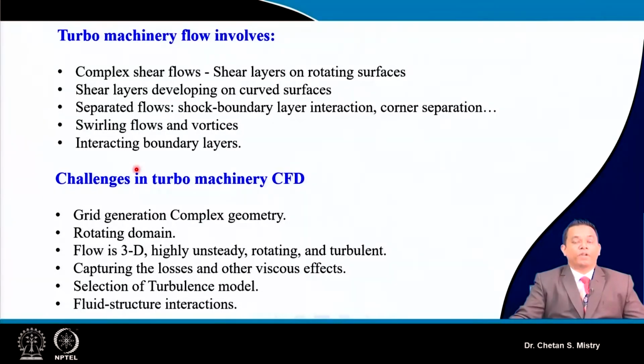Now, when we are talking about the application of CFD, there are certain challenges. The very first is the generation of grids. That means in order to discretize the fluid domain, we know our blade shape, which we get using different approaches, say different wall distributions, that give the three-dimensional shape to my blade. And for that we need to do the discretization, the meshing. That is very challenging.